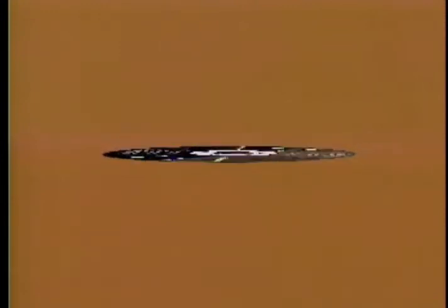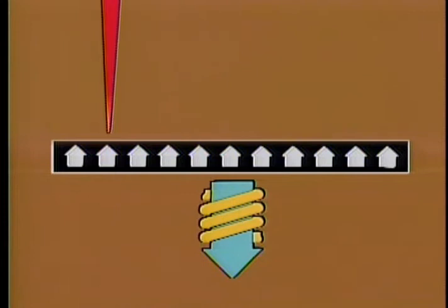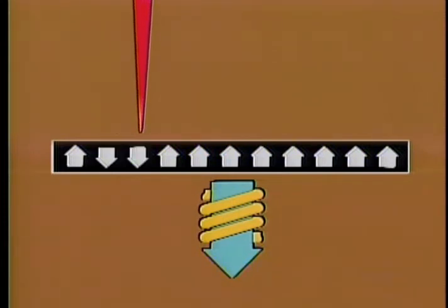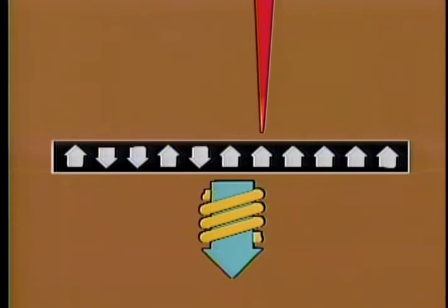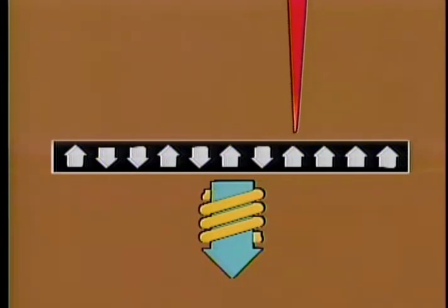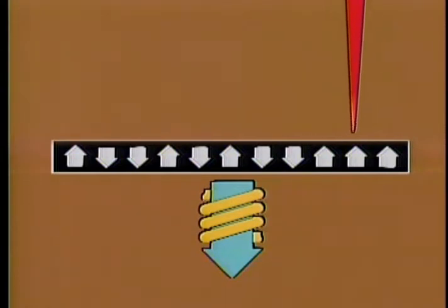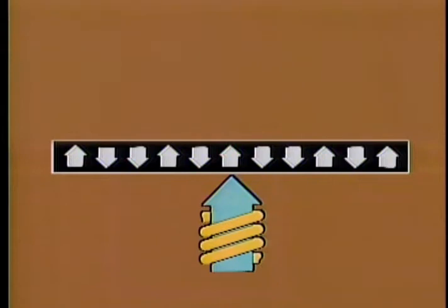3M erasable disks use magneto-optics to record or change data on the disk. Magneto-optics uses the laser to heat small bits on the surface of the disk. At a certain temperature, these bits change their position to match the polarity of the magnetic coil. During reading, a lower power laser senses the changed position of the bit and interprets it as information. To erase, the same power is applied from the laser as was used for recording. The field of the magnetic coil is reversed, and the bit is coerced back to its original position.